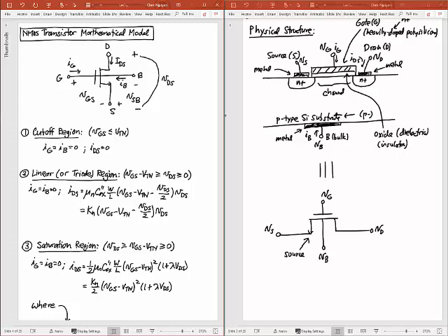Okay, I've basically redrawn right here everything that's down here. Now with all the different currents, I've got maybe a gate current going there, maybe a bulk current going there, but certainly an IDS that'll go from drain to source. And that would be my drain source voltage across that, and then so little VGS, well, VGS here is going to be an important voltage, and so is VDS. So it's just like that generic transistor that I showed, except now I'm showing it with the MOS symbol here.